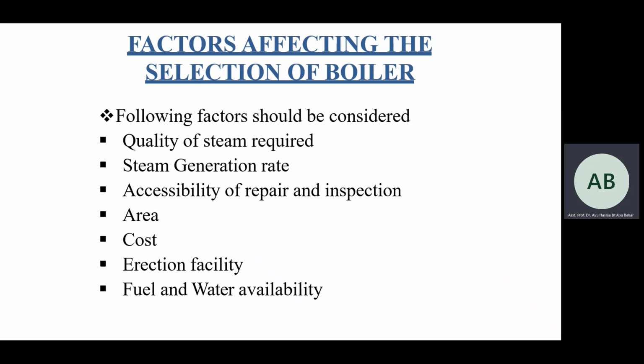For boilers, there are a few factors affecting the selection. The quality of steam that you require, how much steam you want to generate per day or per hour, the accessibility of repair, the area, the cost, and the erection facility, which is the installation of boiler facilities, that means the facilities to lift up the boiler. Then fuel and water availability.